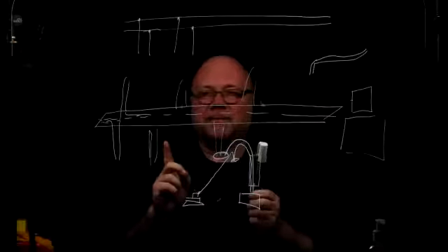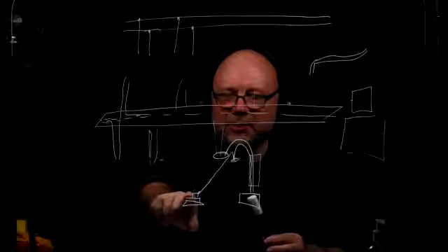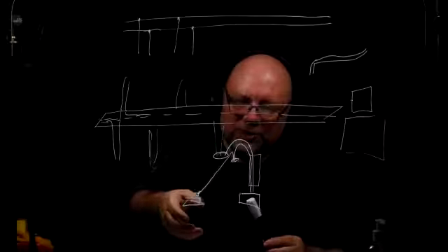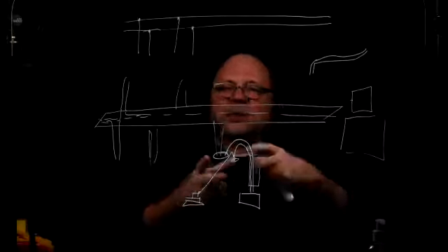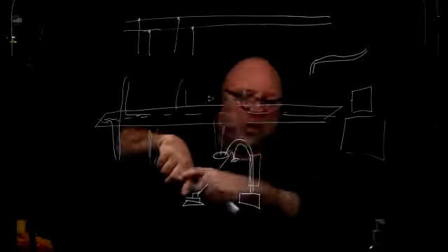When it comes to tapping, the step-down transformers on the speakers have taps. Again, what does it mean? The low side of the transformer, the low impedance, is 8 ohms. It's connected to the speaker that has 8 ohms impedance, and that's permanently connected.